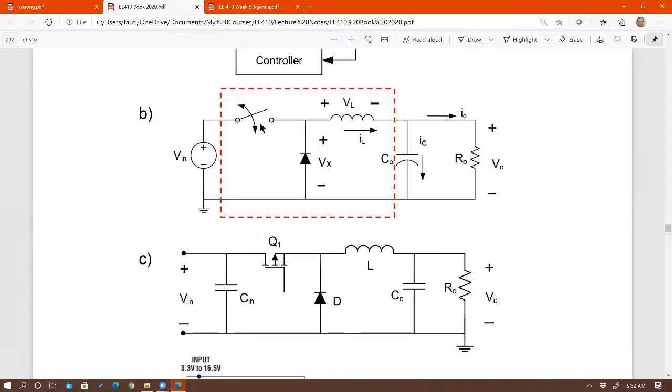Of course, in addition to these three main components, you also have other power components, such as the output capacitor, which is needed to get better DC at the output, because we want DC to DC. Remember that, right? We want DC to DC, meaning the input characteristics will be flat, both voltage and current, assuming that we have an ideal voltage source here. So of course the voltage is going to be flat, but that doesn't necessarily mean that the input current will be flat. You'll see.